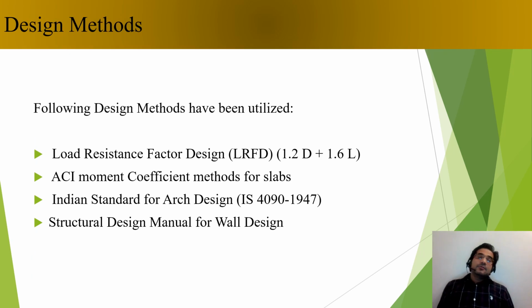As I told you, this building was designed back in 2015, so we have tried to use the load resistance factor design following American Concrete Institute ACI 318 building design, where we mostly utilized the 1.2 times factor on dead loads and 1.6 times the live loads. For the slabs, we have tried to utilize American Concrete Institute moment coefficient measures, and for the arch design, we have used Indian standards IS 4090-1947. A structural design manual was used for the wall design.